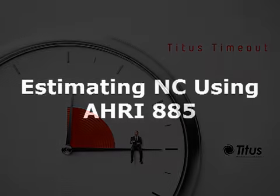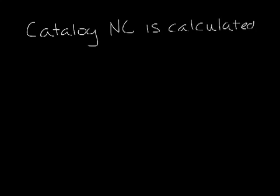I'm Jenny Abney-Civi, and today I'm going to discuss estimating NC using AHRI standard 885. A little while ago we discussed sound power in NC, but what I didn't really get into is how NC is calculated. Catalog NC is not a measured number. It's calculated from the unit sound power using AHRI standard 885.